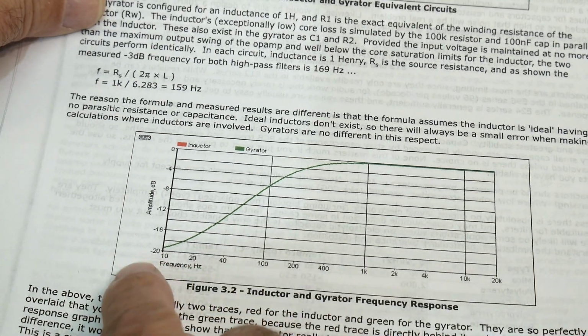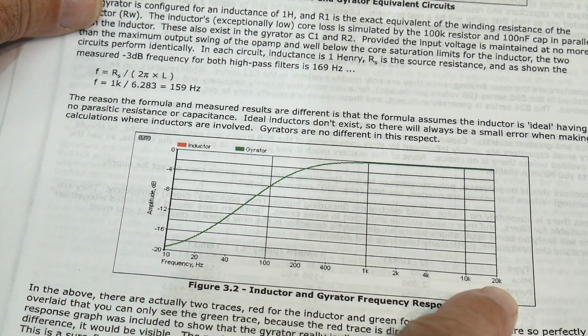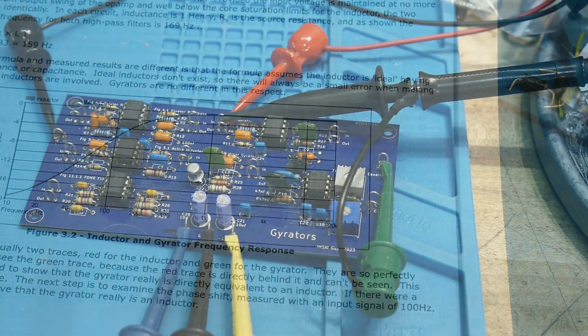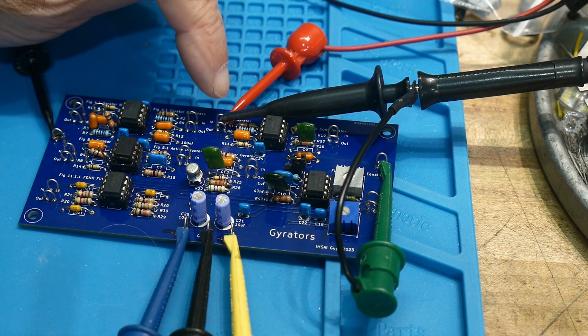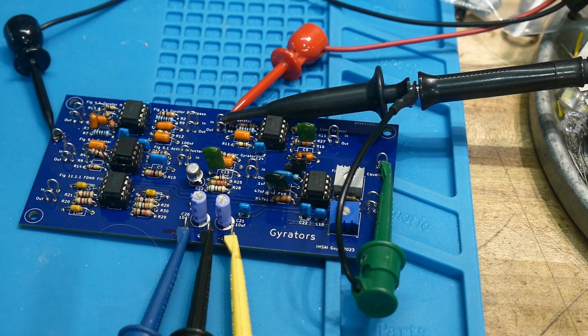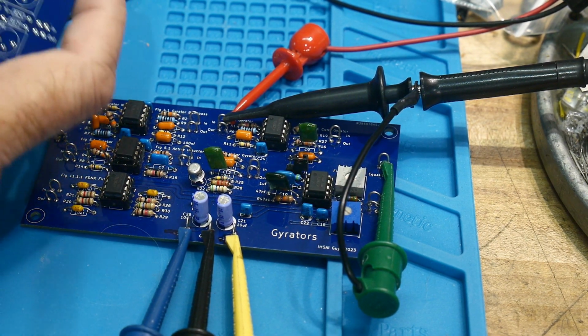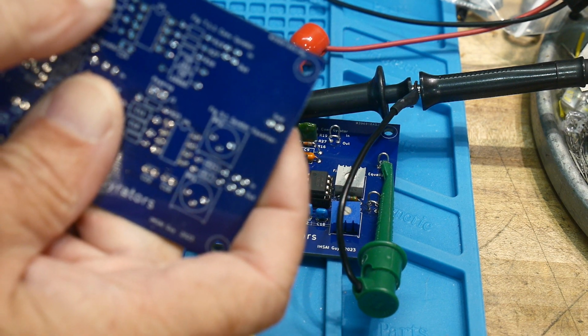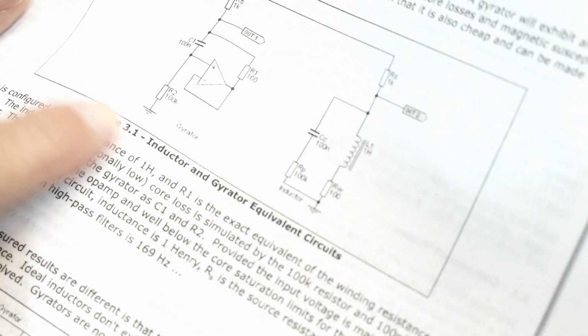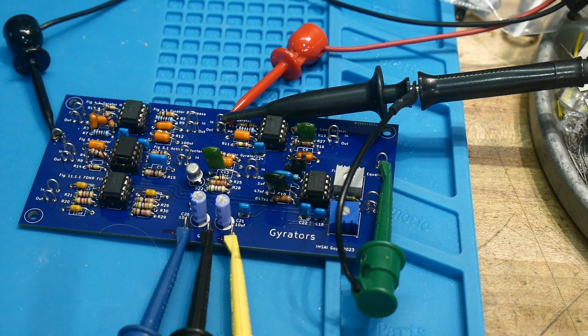And we should get something that looks like this high-pass filter here. This sweeps from 10 to 20K. And we should see this type of curve. So let's try that out. All right, and so the filter input and output that we want to deal with is over here. It's labeled on the PC board, figure 3.1 gyrator. So if you get one of these boards, this is figure 3.1. The PC board will say figure 3.1 is the place that you should be looking at.